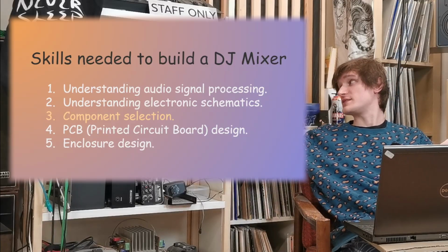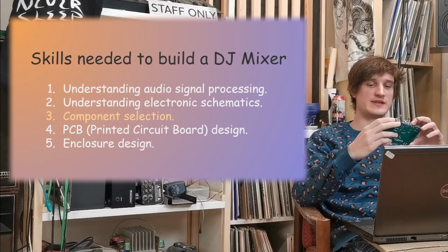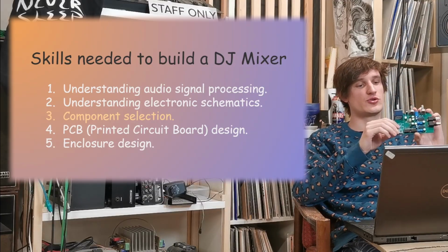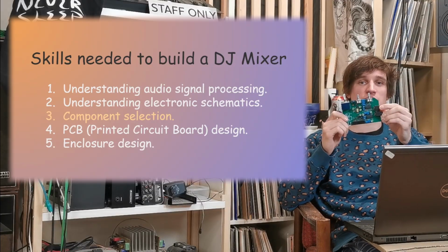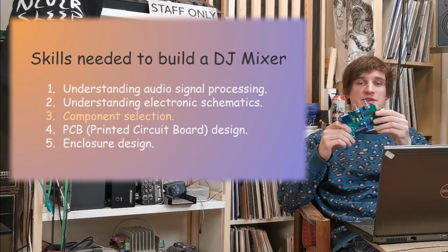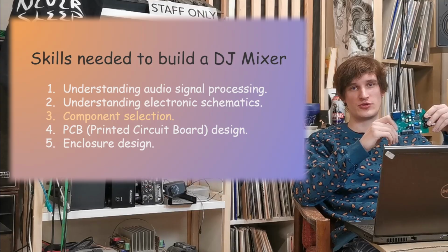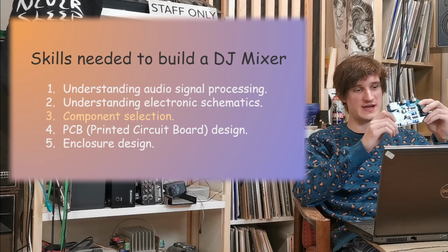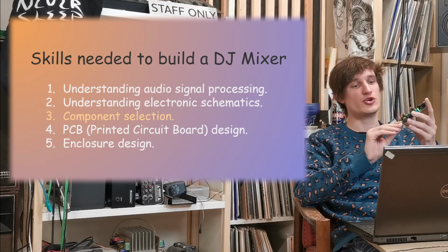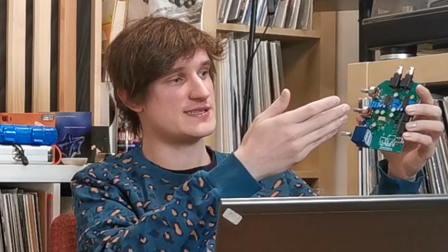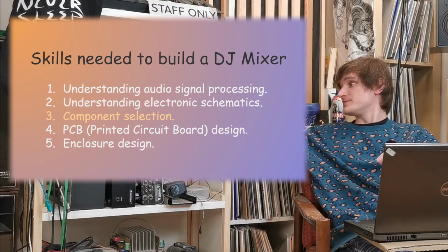And to make the design work and to make it elegant, you want to produce a printed circuit board with all the elements here. But before you make this board, and on the next part we'll talk about printed circuit board design, before you design the board, you must find all the components you want to place on the board, because you want to know the component sizes to just fit in the board and to make a nice layout.